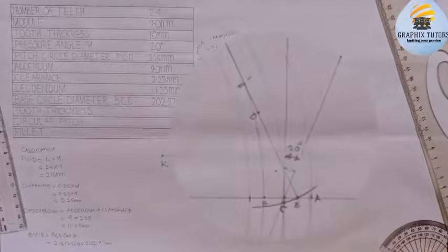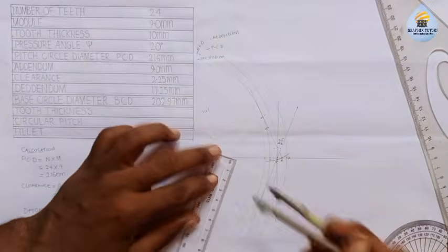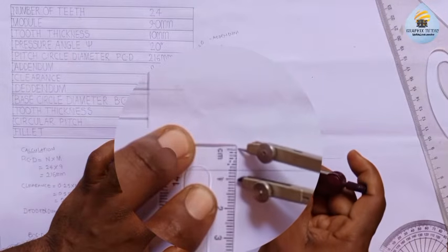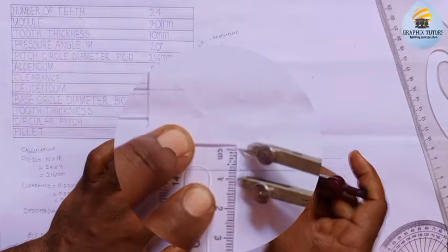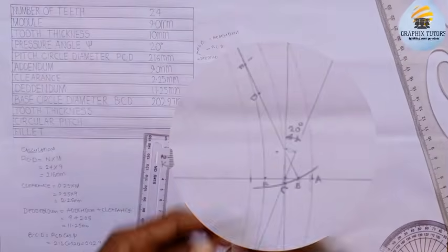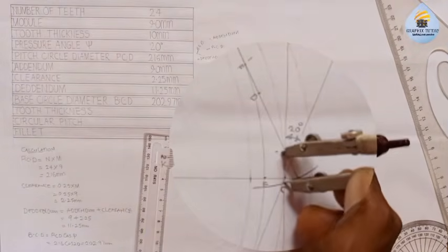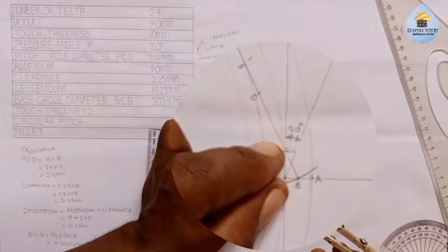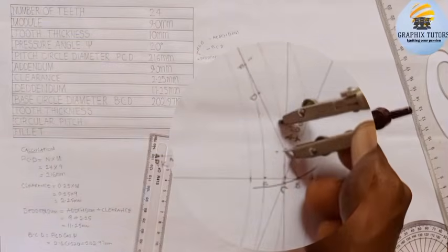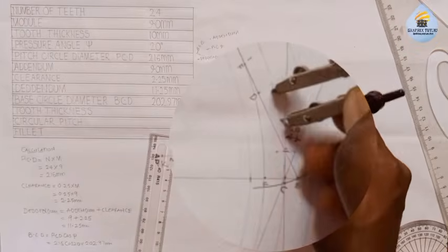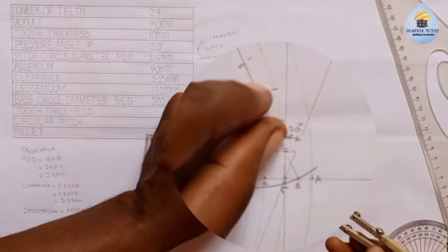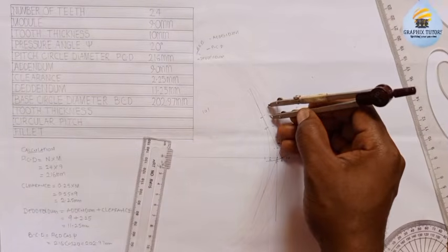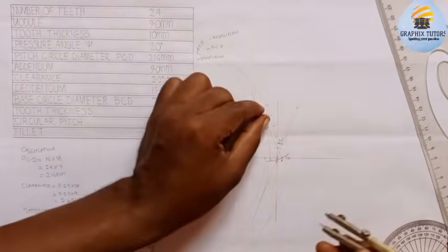So you measure 10 millimeter on your meter rule this way, and at every point from point C, you start marking. So this will be 1. So these two making one tooth. I'll come again, I'll mark another 2 points. 1, 2. This is what? 2 teeth. I'll come again, another 2. 1, 2. That is what? 3.